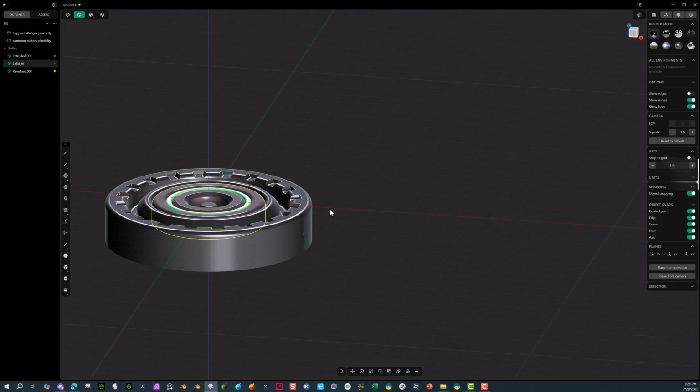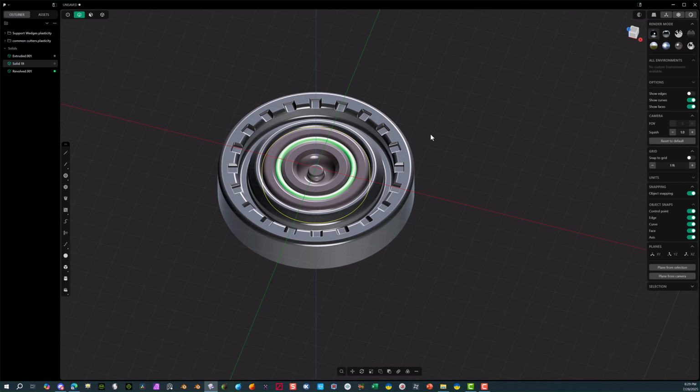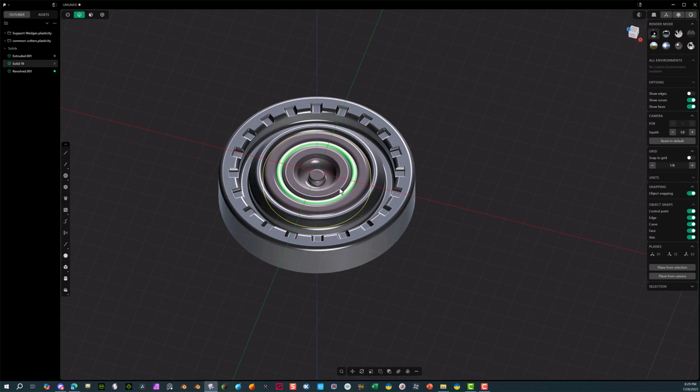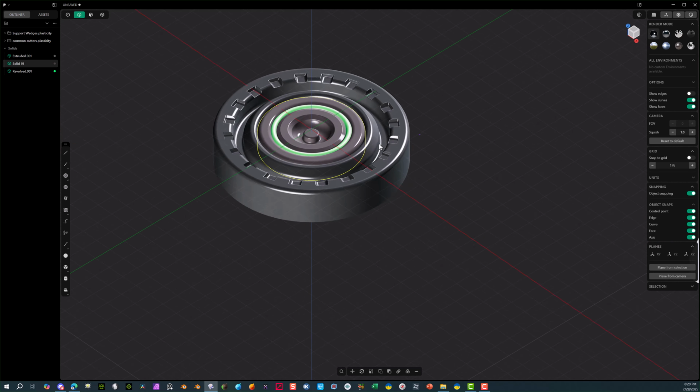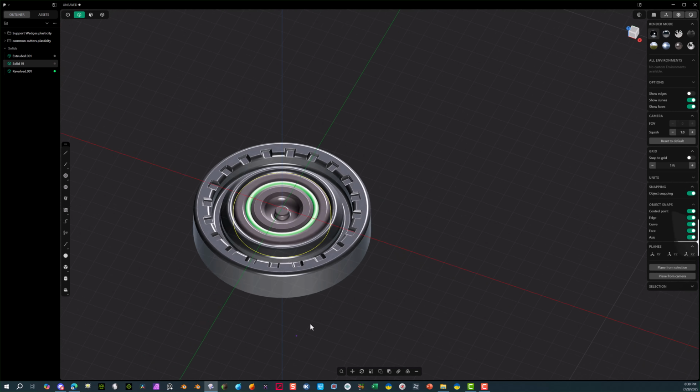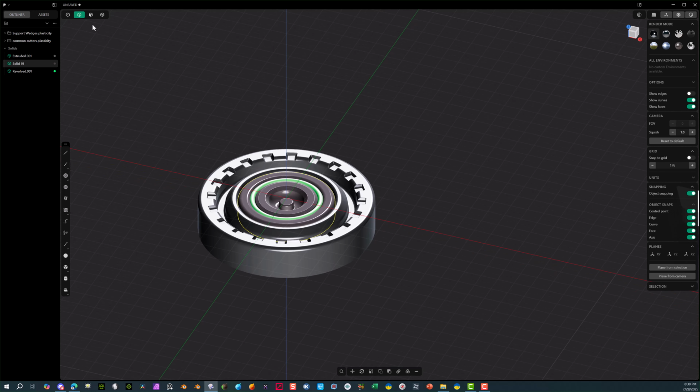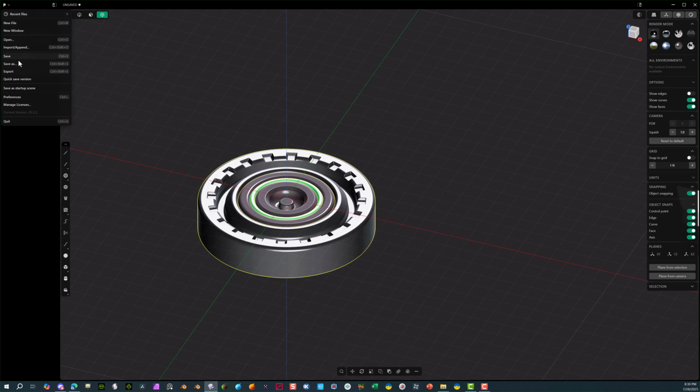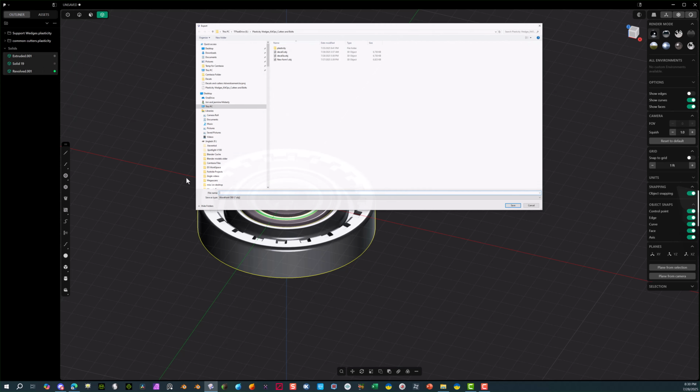Okay, so that's simple. So I'm going to show the basic method of converting this to an OBJ file. I don't want to go through the other process, but I personally like OBJ myself. I just feel it's easier for myself. So there are other ways to do this, of course. But anyway, for now, I'm going to select all these here. I'm going to go back to the top here. I'm going to say export. And I'm going to call this Decal 4. And I'll say save.